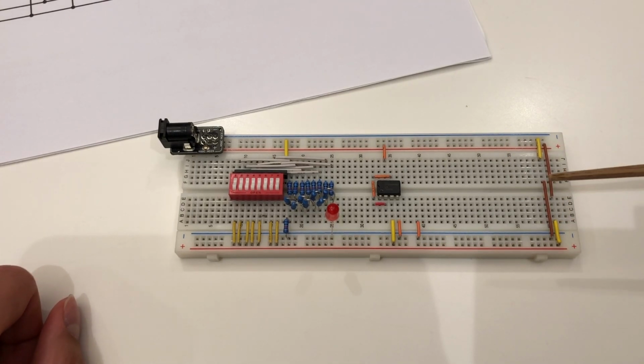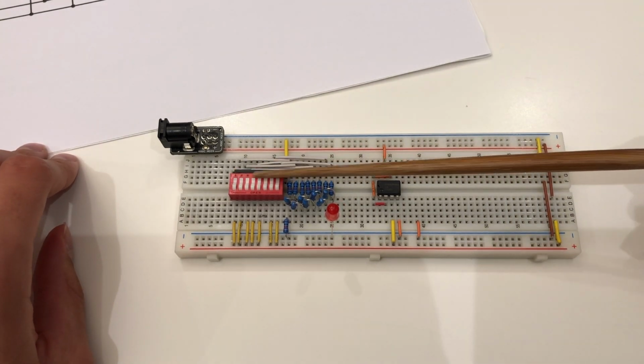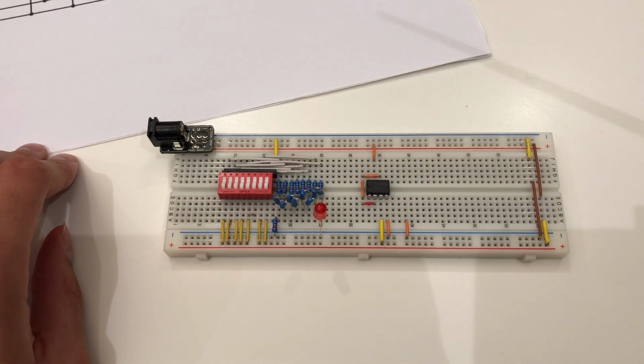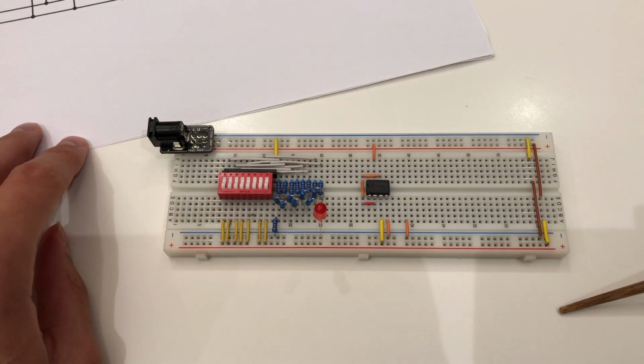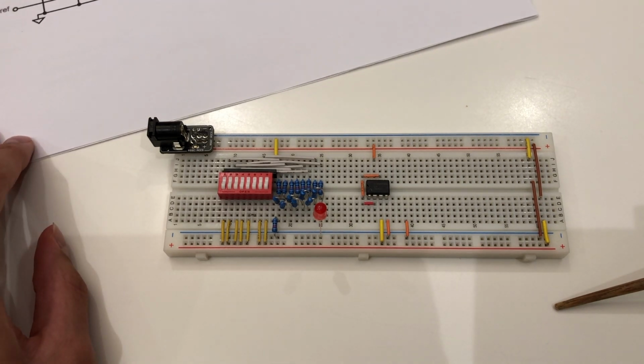The purpose of the R2R resistor ladder is to convert a digital input on a set number of bits to an analog output on which the different levels of voltage dialed are displayed. The R2R resistor ladder serves as a digital to analog converter, or DAC, which is needed for digital devices to approximate varying analog voltage levels so they can work with real-world signals.